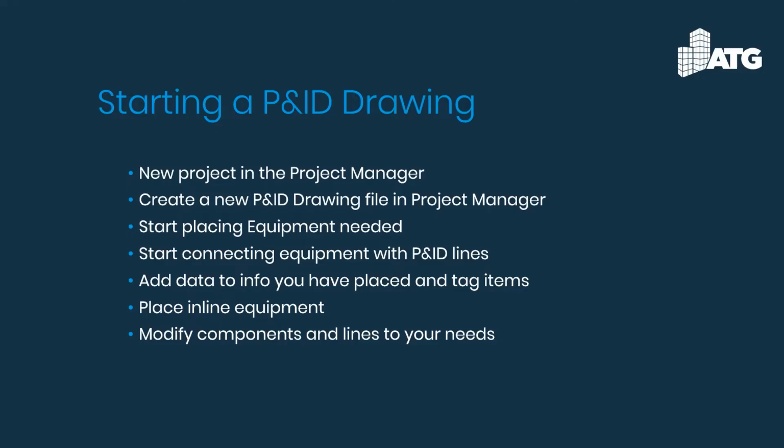So P&IDs can already be added to an existing project. But if a project has not been started, we can go through the process of creating a brand new project. And then within the project manager, there's going to be an area where we can create a new P&ID drawing file. So you'll see those different areas when I get into Plant here and show you the project manager.